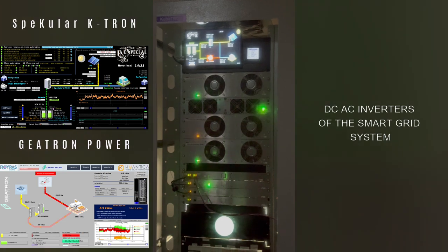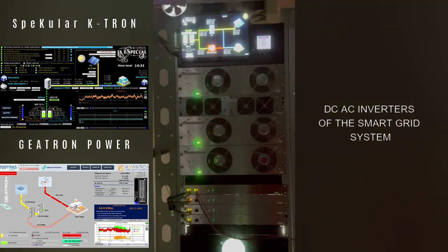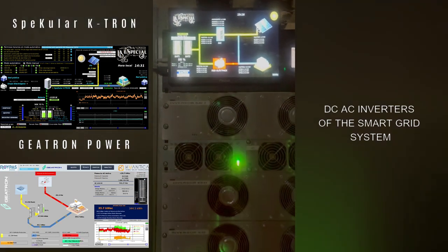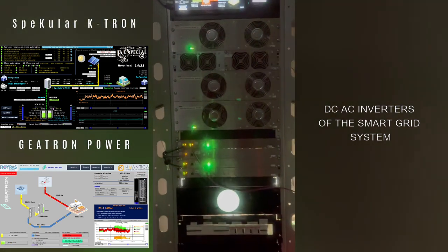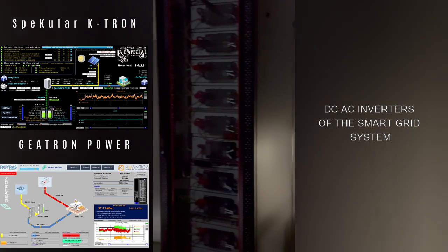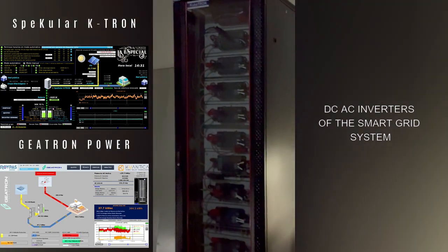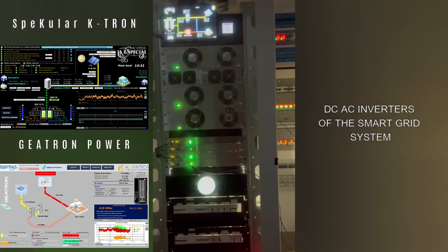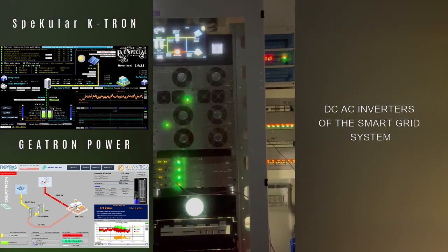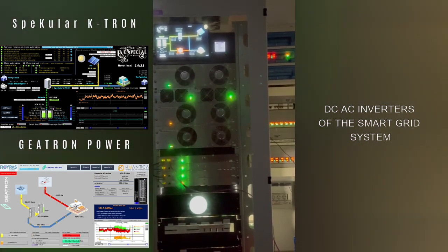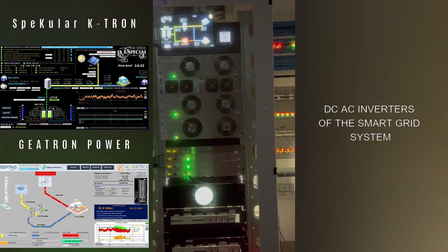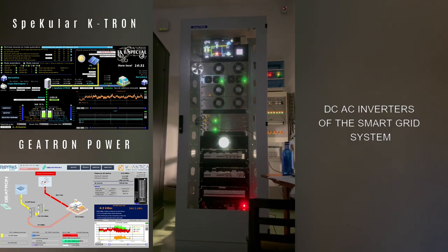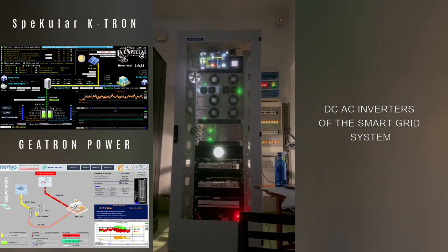Overload capacity in grid forming mode is 125% for 10 minutes, 150% for 1 minute, and 300% for half a second. In grid forming operation, consumption is divided by DC-AC equipment, allowing distribution to be determined. Power factor operation in all 4 quadrants of operation. Compensation of phase imbalance, up to 100% of one phase supporting asymmetrical consumption. Simultaneous reactive power generation, without penalizing active power generation capacity.